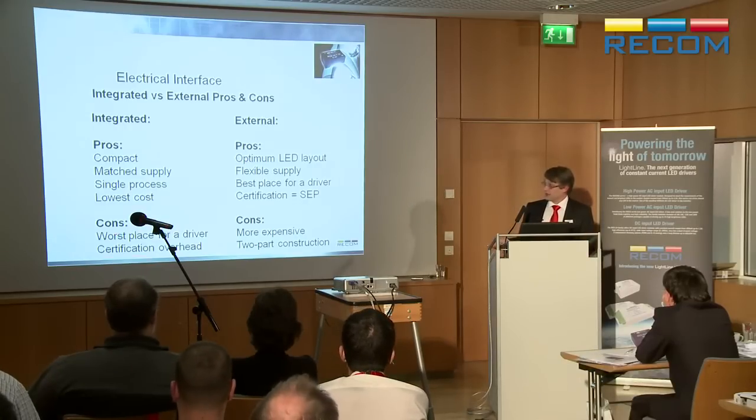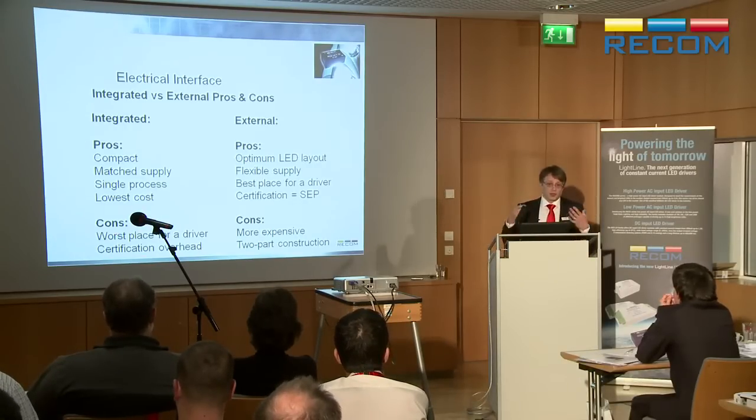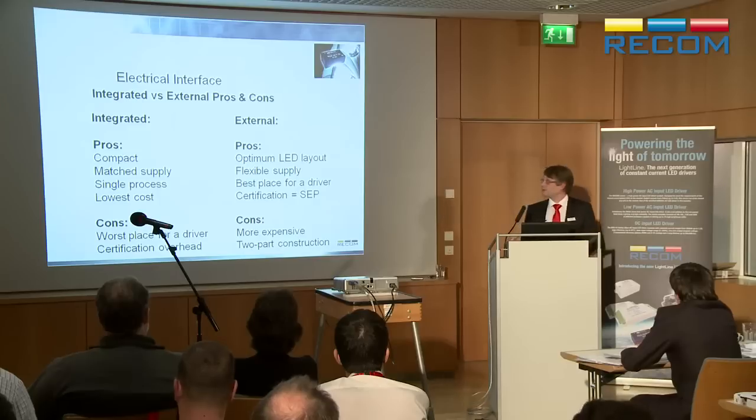And the other problem is certification. By that I mean that you have to certify the whole system for EMI and stuff like that. So if you've got lots of separate systems all joined with long cables, trying to make sure that you don't have any EMI problems, no interference between the different systems, is quite tricky.